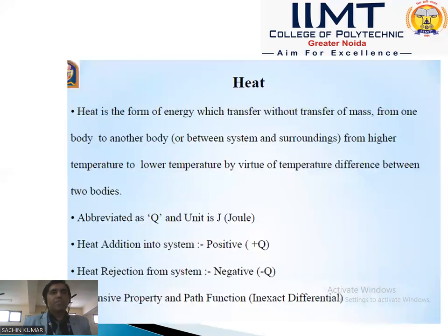Next we will discuss what heat is. Simply, heat is a form of energy which transfers from one body to another without transfer of mass. If heat is added to the system, Q is positive, and heat rejection from the system is Q negative. Heat is always a path function, as we discussed in the previous slide.